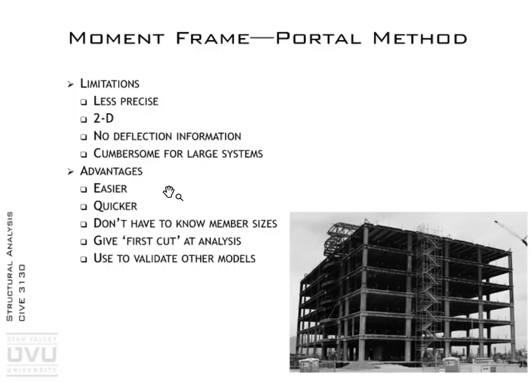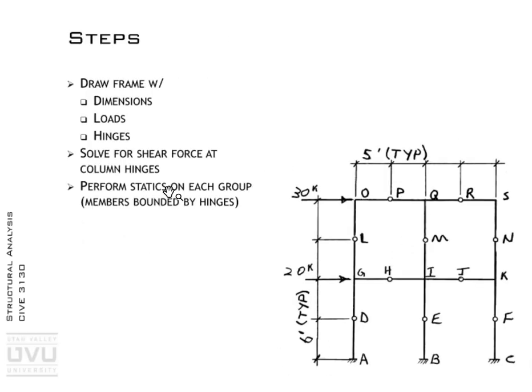In half an hour, you could calculate the basic loads for the building, do a quick portal method, and size the member based on these moments and shears, rather than spending days developing a structural model of this animal. Maybe it takes an hour or two, I'm probably being overly optimistic about half an hour, but in a short period of time, you could have a preliminary design of this frame to the point that you could answer the question you were asked, and then down the road, you can do the in-depth engineering analysis and design to get your final drawings put together.